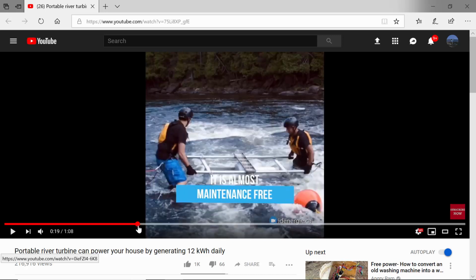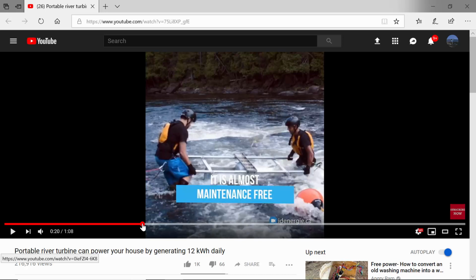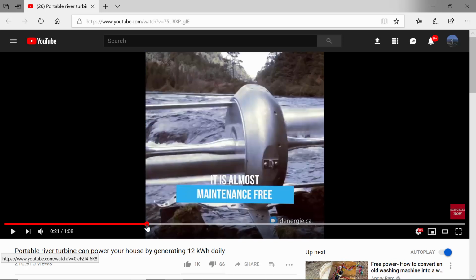So ordinarily, the types of hydropower setups that we've been talking about so far in this semester have been some elevated reservoir, and it was connected to a pipe. They're called penstocks, where at the end of the pipe is a generator, and then discharging from that generator is a lower reservoir. And so the way that we calculated the power that was available, the power equation, is the flow rate times gamma times H sub T,